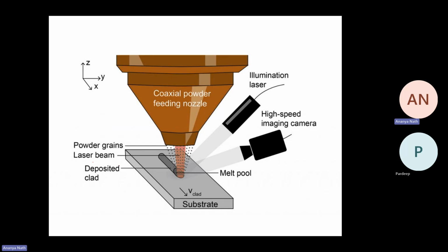Second last, we have the DED process, where we can use arc, laser, or plasma as an energy source. Here, laser is being used as an energy source, and wire or powder both can be used as a raw material. DED is a process which can print only and only metal, no polymer or other material. This is only useful for metals.